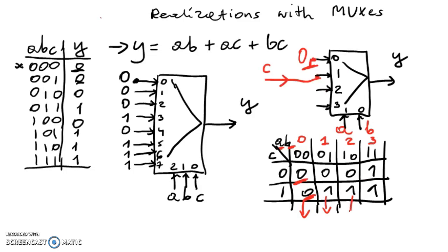All right, so the same is here. So it is a C, 0, and 1 here. So here we must short circuit the two inputs and connect to C, and here you must put 1. It is the same as plus 5 volts static voltage, okay, high voltage. And that's it. It is also the same, but as you can see, the multiplexer is very small compared to the previous one. Yes, you can compare the inside of the multiplexer in the lab.